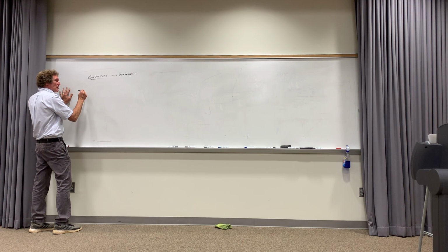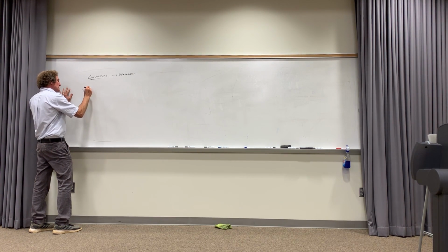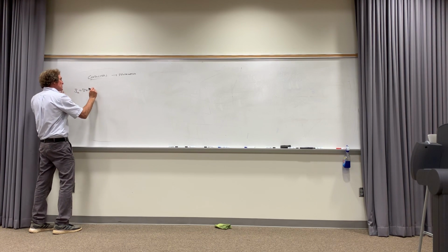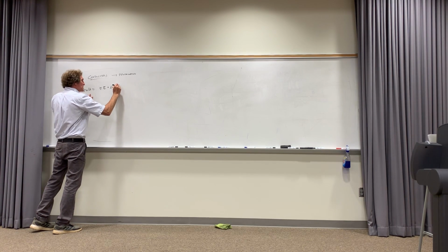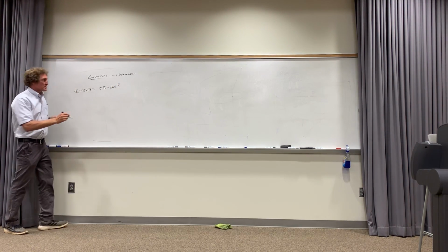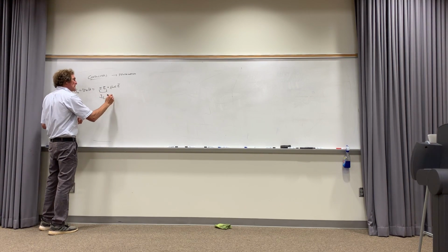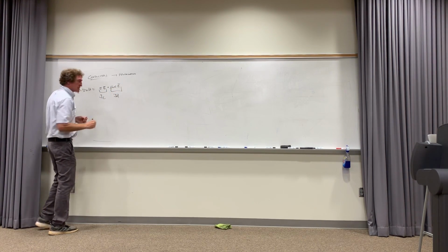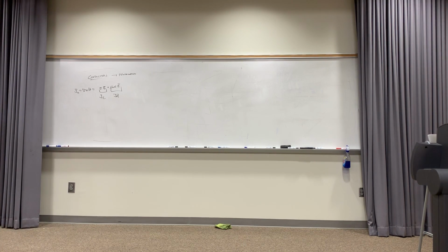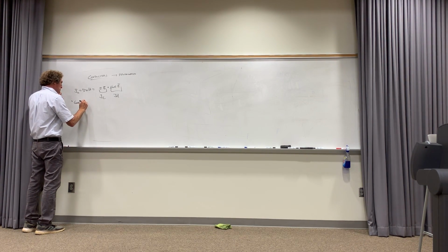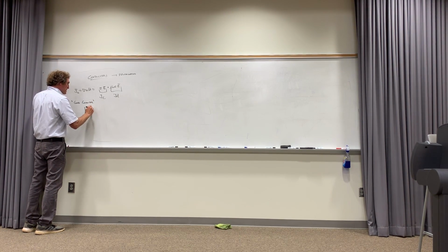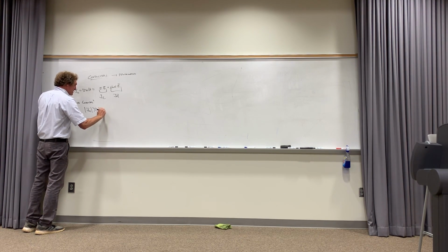So if you think about what a conductor is, go back to Maxwell current density. That's equal to J Maxwell. That's equal to really sigma E plus J omega epsilon times E, right? This is conduction current density, and this is displacement current density. You've heard those terms the last time you took EMA, right? So if you have a good conductor, what you're really saying is that the conduction current density is much, much greater than the displacement current density.